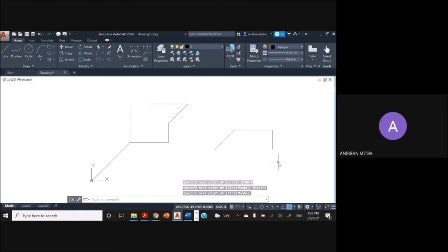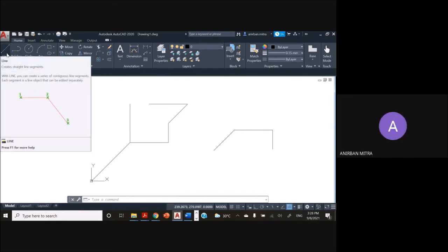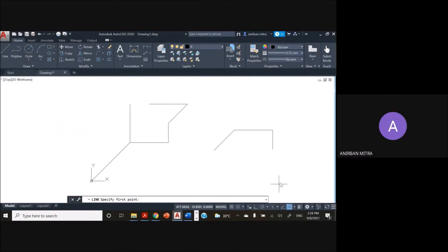Just try to think about, if I want to draw a rectangle of length 100 and height 75, what will I do? What commands do I need to provide? Sequential. First, specify the first point. Then you want to move in the positive x direction, and the length is 100. So @ 100.